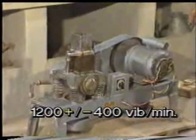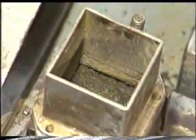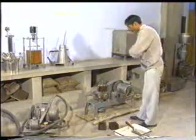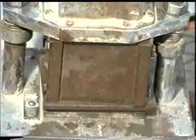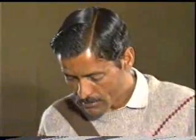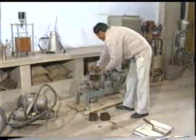This vibrating machine has standard vibrations of 1200 plus minus 400 vibrations per minute. The cement cubes are compacted by giving standard vibrations for 2 minutes. Switch off the vibrating machine after the stipulated time of 2 minutes. Unclamp the mold.